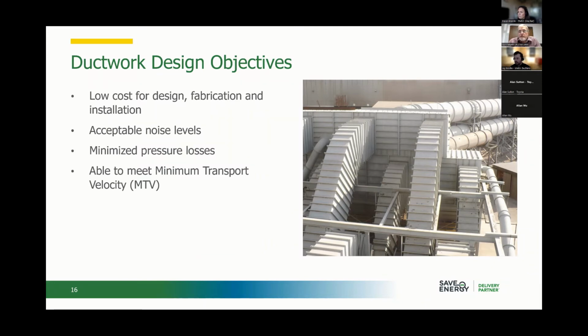Whatever, every process will be different. And so the ductwork has to be designed in such a way that the velocity is high enough that you don't get a settling out effect. That's the worst thing that you have is settling out. A typical, and I'm sorry, I'm an imperial units guy, and the typical number that you would often see in the industrial world is 4,000 feet per minute. Well, that's a pretty ripping good flow coming down your ductwork.